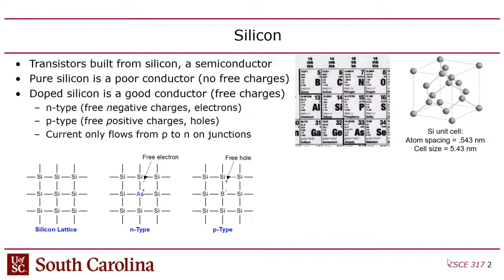So last time we introduced this topic, and I started out by explaining how semiconductors work. You start out with a silicon lattice, which is a crystal where atoms are arranged with covalent bonds with 4 of their neighbors at various angles, and has very poor conductivity, but you can add a dopant into the crystal structure, which replaces some of the silicon atoms with atoms from either group 3 in the periodic table, column 3, or column 5.